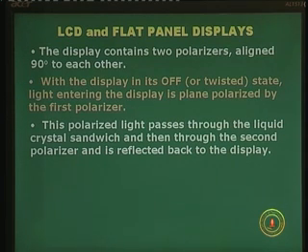So, in fact, when the display is off, the light is allowed to pass through these layers: the first polarizer, the sandwich layers of crystals in between, and also the second polarizer, which, if the first is horizontal, is vertical. The light is allowed to go and fall on the display, and we see that portion of the LCD illuminated.